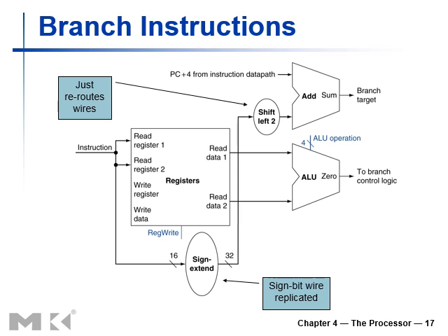Now this is a setup. Basically, we have a 32-bit machine code from the instruction memory, and we have extracted those 16 bits of the label. We have sign extended those 16 bits to convert them into 32 bits. Then we have to multiply by 4, which is why we are using shift left 2.